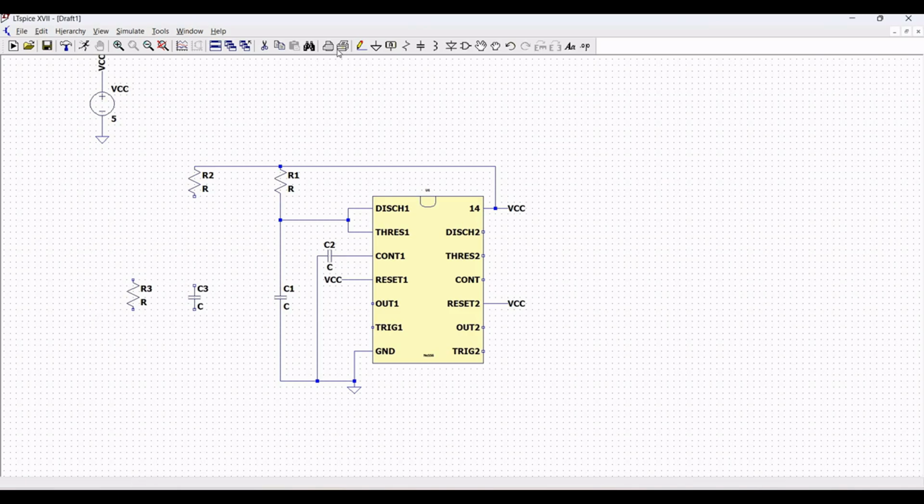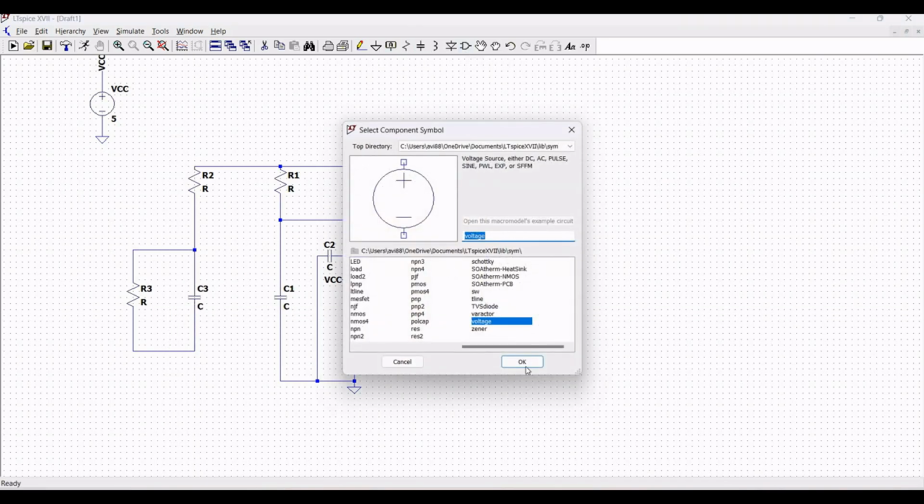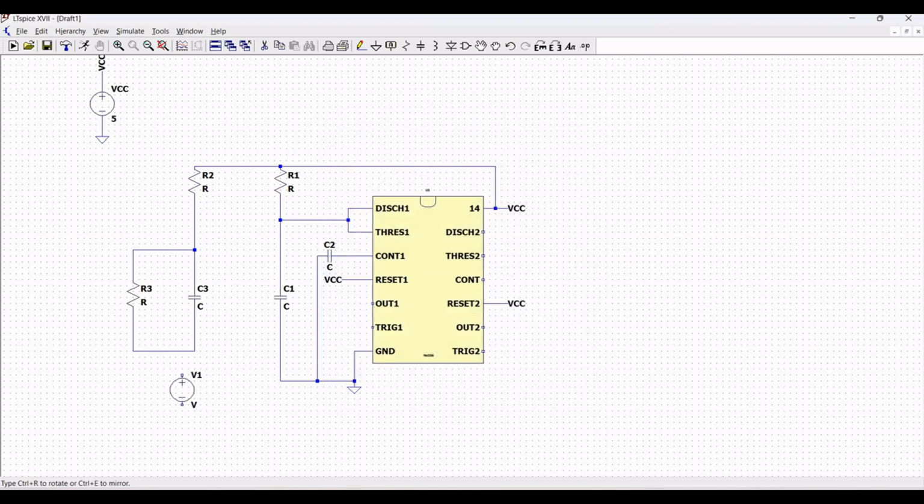Make the appropriate connections as shown in this particular tutorial. Both the timers are connected in their one-shot mode. Grounding the trigger input starts timer 1, which then starts timer 2. We must define the value of each resistor and capacitor for this particular given schematic. Now define all the values of the resistor.